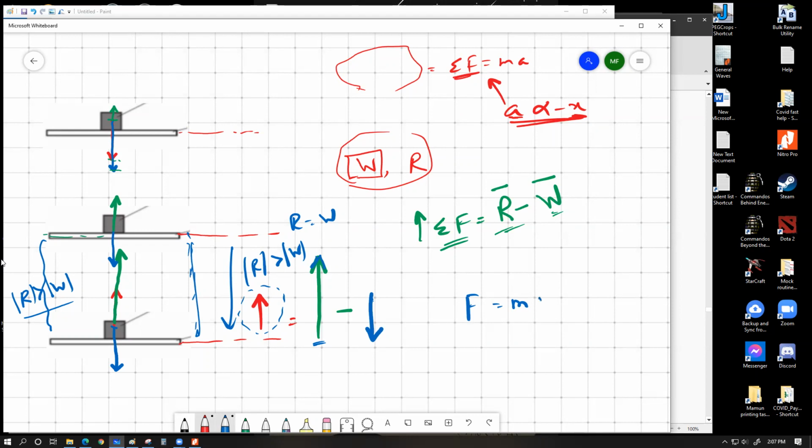So F equals m omega square R, and I can write F max, the maximum force, would be m omega square A. So if we slowly start to increase the amplitude of the particle, the F max will also increase. This is basically, I'm talking about the red force. So I should have written this in red. Consider this all written in red. So the maximum resultant force that we're going to require should be coming from m omega square A.